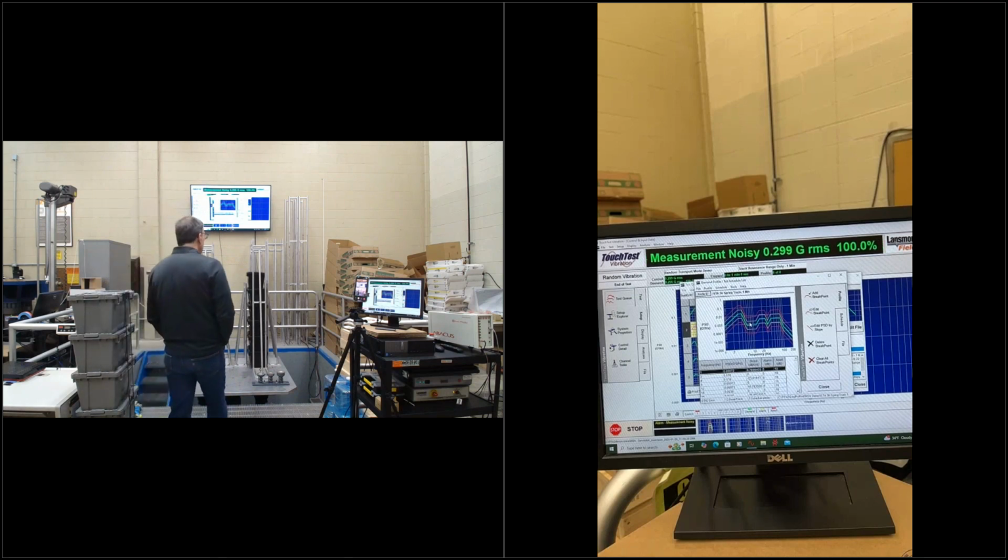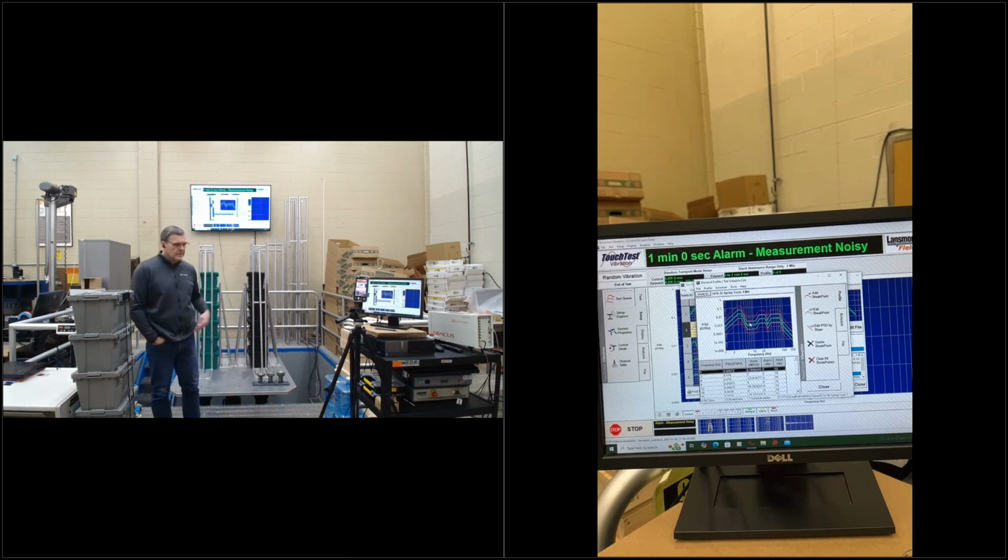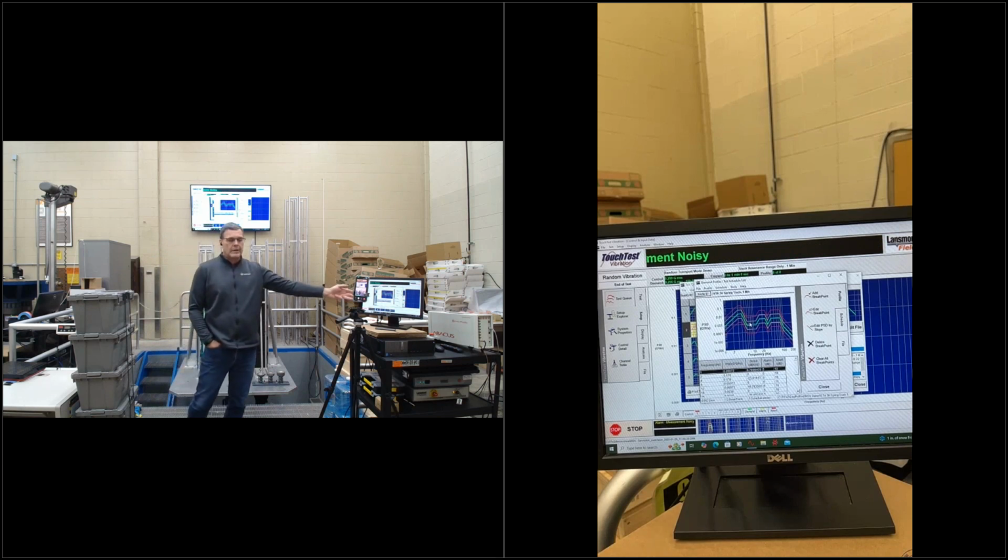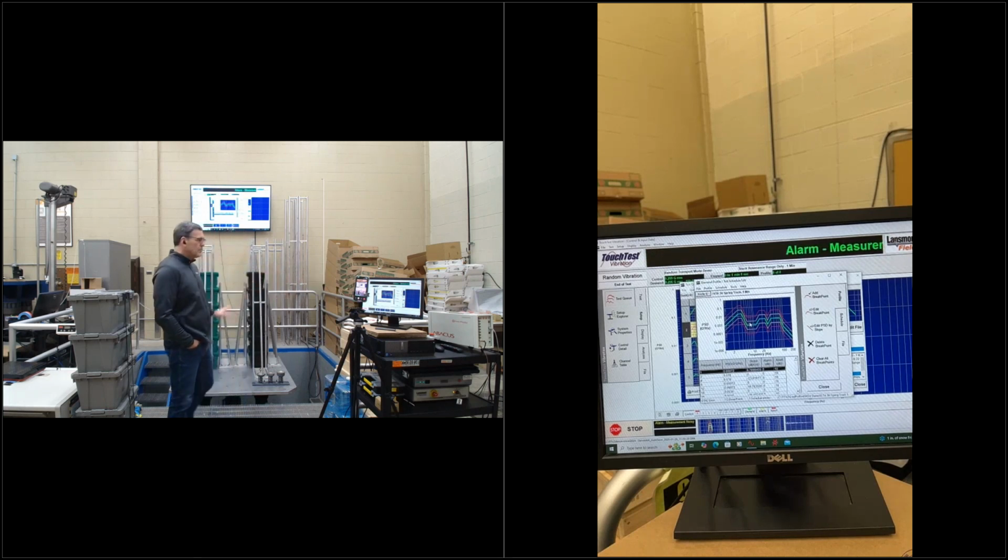Tough one to answer, because I don't quite understand the question, I apologize. But those kinds of questions depend on what the natural frequency characteristics are of the product and of the packaging or lack thereof, and how durable the product is. If it's a fragile product, which you have to determine through product testing before you ever consider putting it on a pallet or on foam on a pallet, you have to ask how sensitive is it? Maybe it's super robust, and you don't have to worry about vibration.